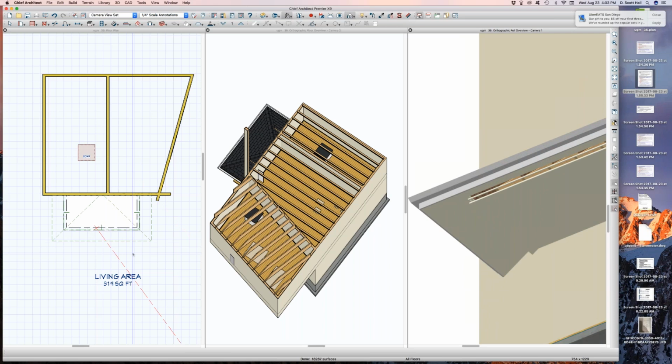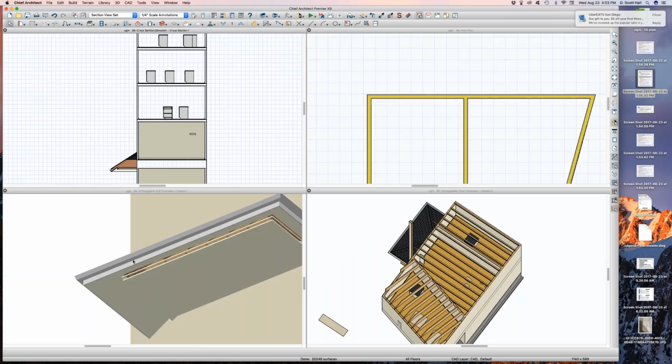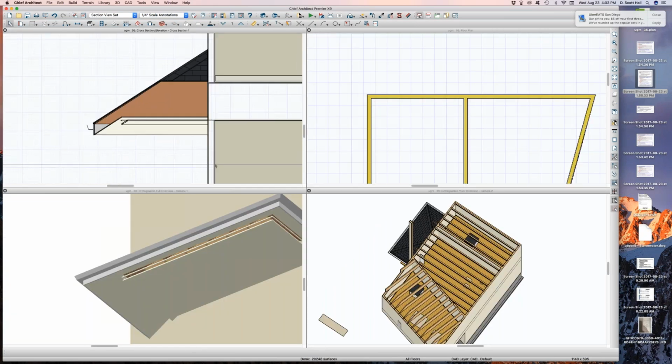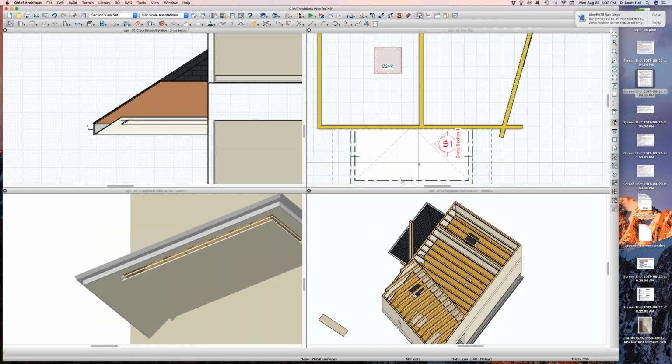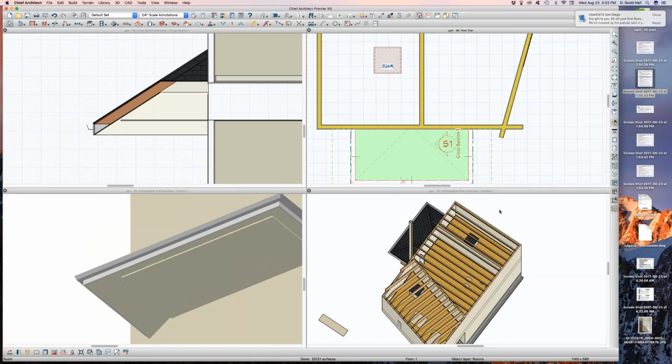So set the room to use the soffit as a ceiling, and it should clean it up. Okay, I'm going to do what you just asked me to do, and just click on the roof. So you guys know what it is. Here it is, right here. And so now you want me to? What do I need to do, Chop? Open the room. Yep. That should fix it.